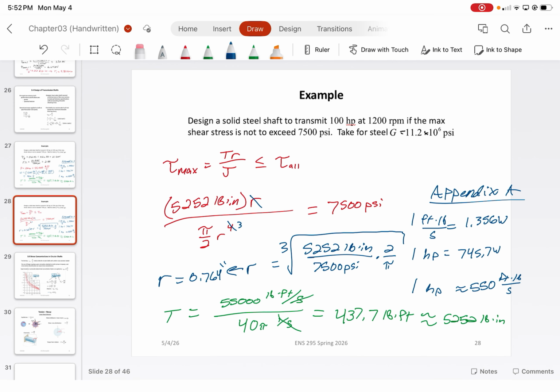2.8. Yeah. So if you wanted to reduce the factor of safety a bit, for example if code specified you need a factor of safety of 2.5, then the specified shear stress you were provided is a little too low, so you could increase that. So you can technically get away with using a 3/4 inch rod. Ultimately, that's an engineering decision you would make. But in this case, because the problem says to use 7,500 psi, we would need to enforce that.